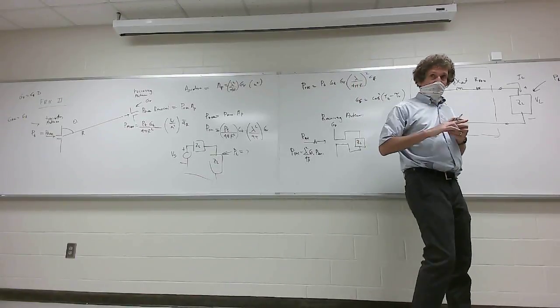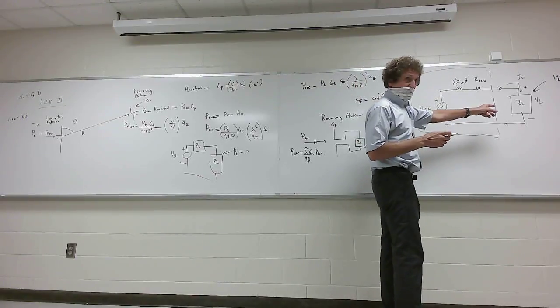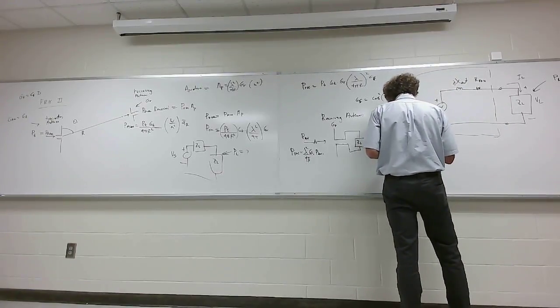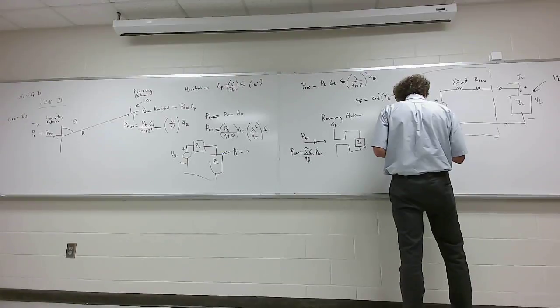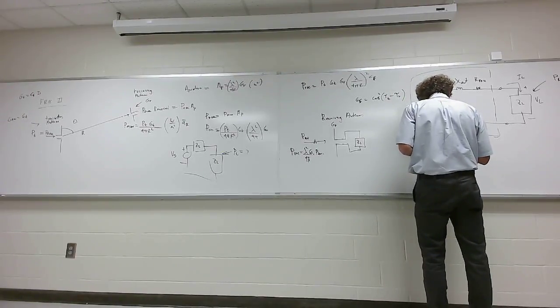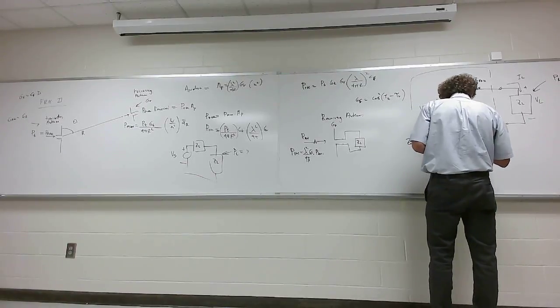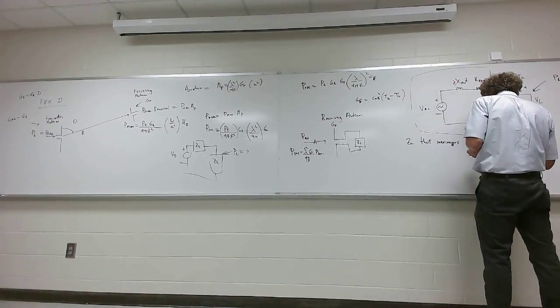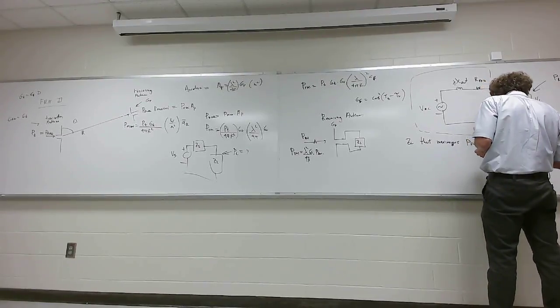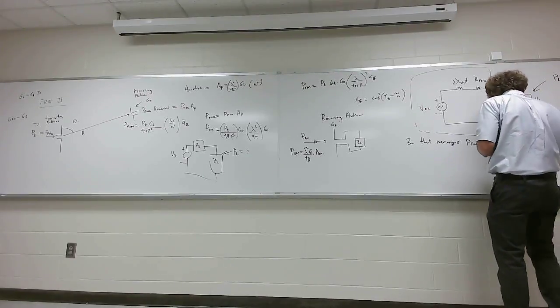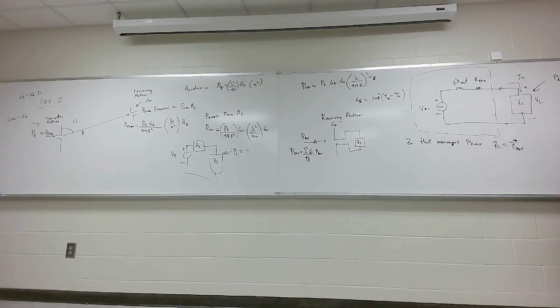Now, the truth is, the value of ZL that maximizes power, write this down, ZL that maximizes power is when ZL is equal to the conjugate of the actual antenna impedance. How many remember that? Let me show you why, and I want to do it over there. But I want to make sure this really sticks with you.